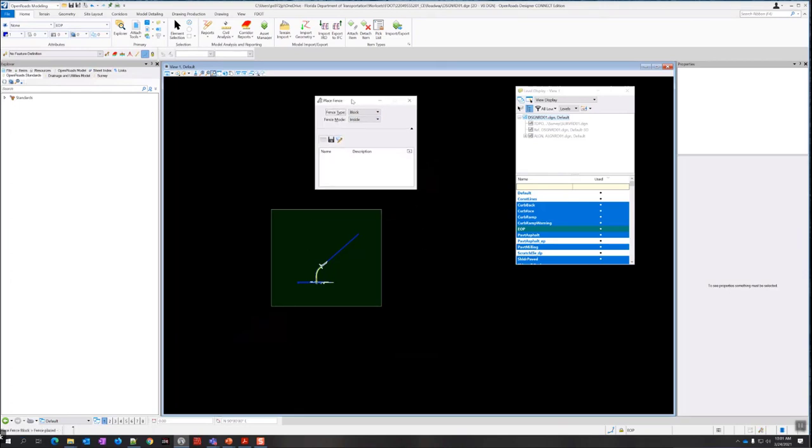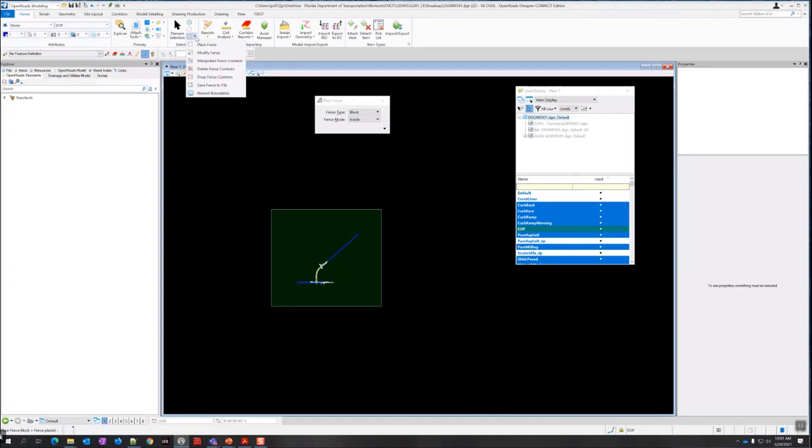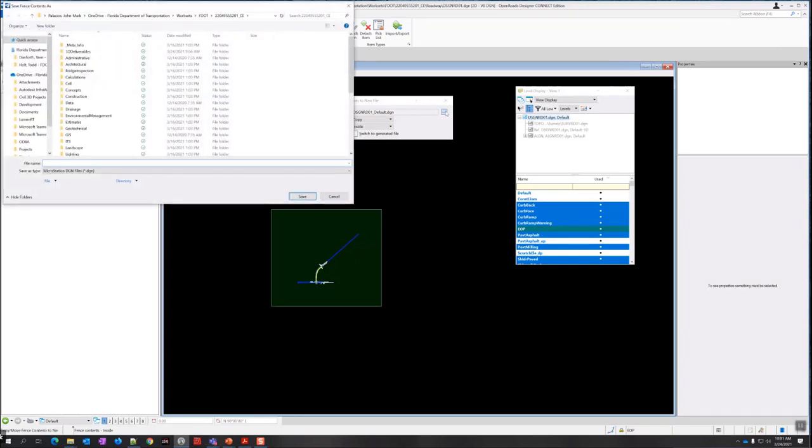So then we want to save the fence contents to a file. So we go back to this option here, click the drop down, and do save fence to file next to the last option. And then we got to check the output file. So the output file is going to be in our 3D deliverables folder. So click that 3 dots there.